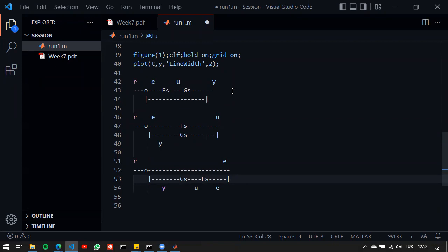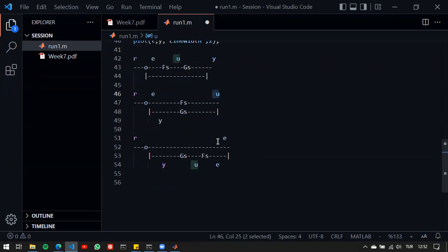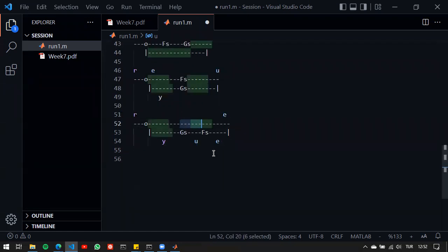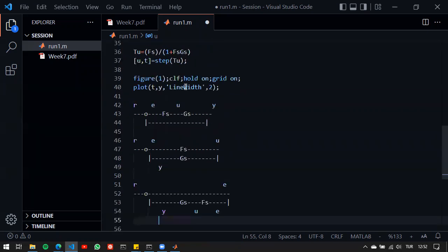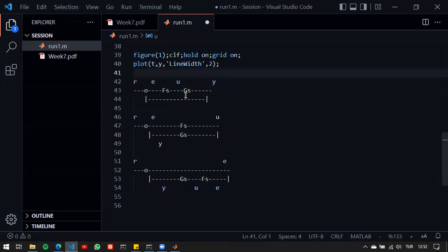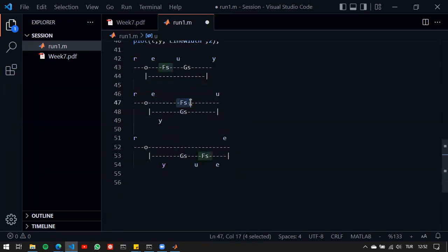The only difference is that we are basically interpreting the output a bit differently. Here, the output is Y, the actual system output. Here, the control signal. Here, the error. And here I can also see that for the error, I have just gain 1. So the transfer function of this should be 1 divided by the loop F times G. So 1 divided by 1 plus FG. Or, as your friend suggested, we can also divide by Fs to get, again, the same effect.